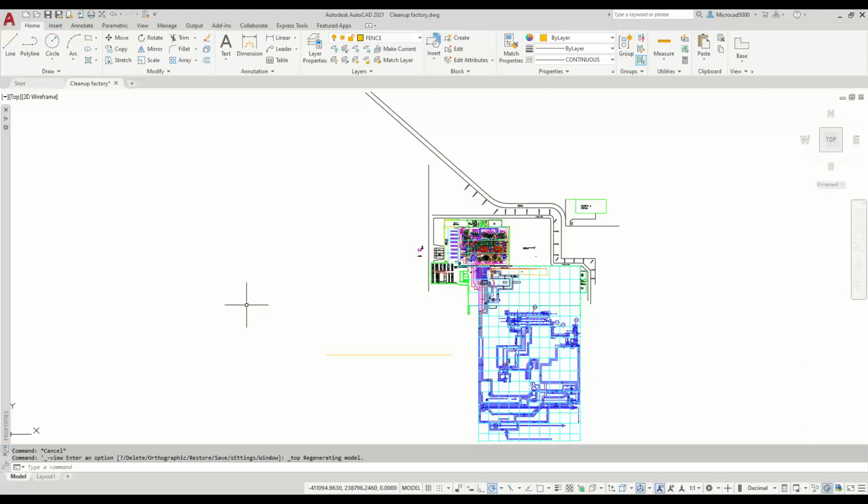And I would suspect that some of you guys out there have probably used AutoCAD LT. So the question is, how do you look at the front edge of a sheet of paper if you're in AutoCAD LT? Because everybody will tell you, oh, you can only work in 2D in AutoCAD LT. You can only draw in 2D in AutoCAD LT. That's what everybody tells you. That's not true. You can work in 3D in AutoCAD LT. And I'm going to show how you can tip this drawing file over in 3D in AutoCAD LT.